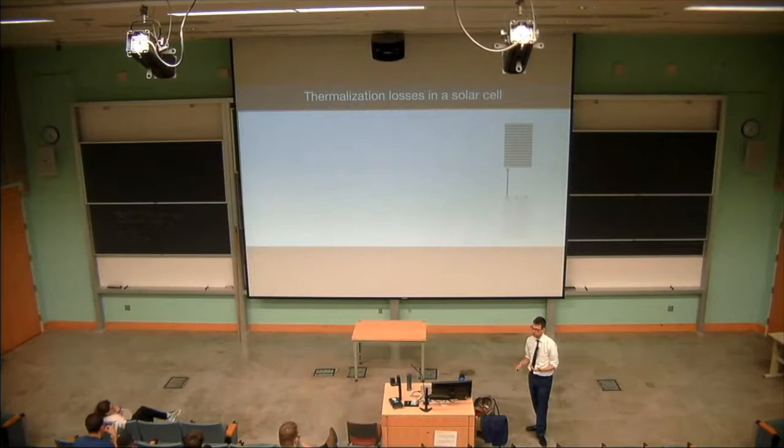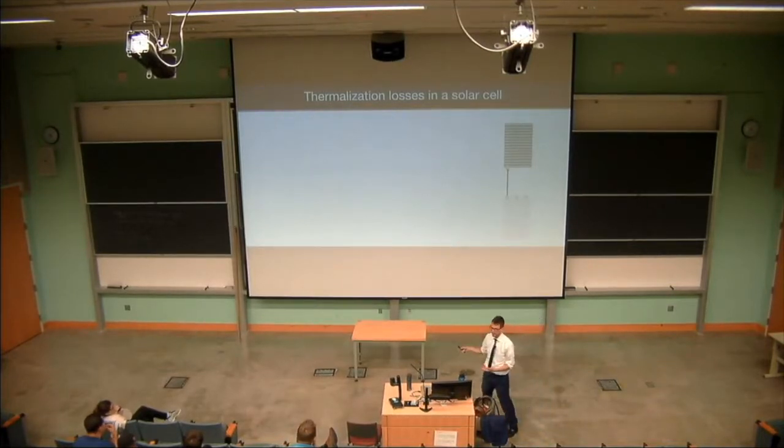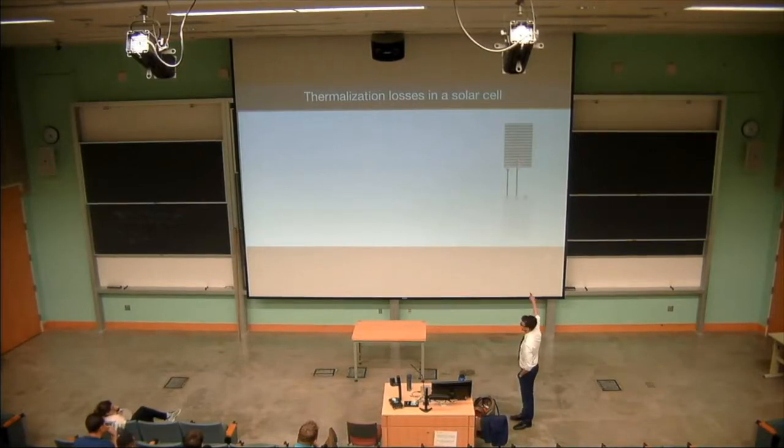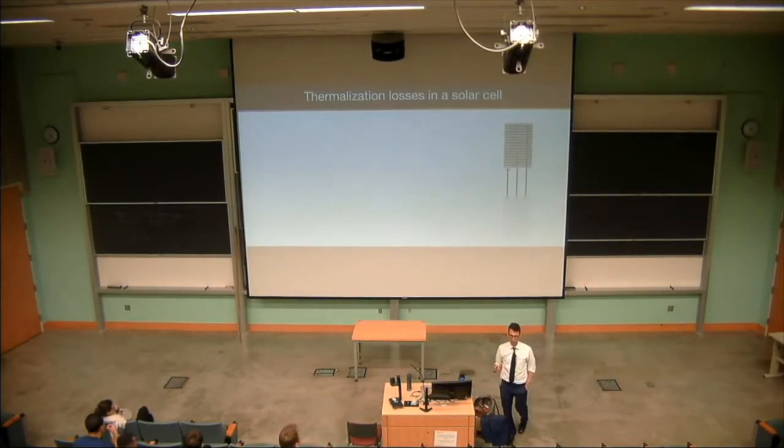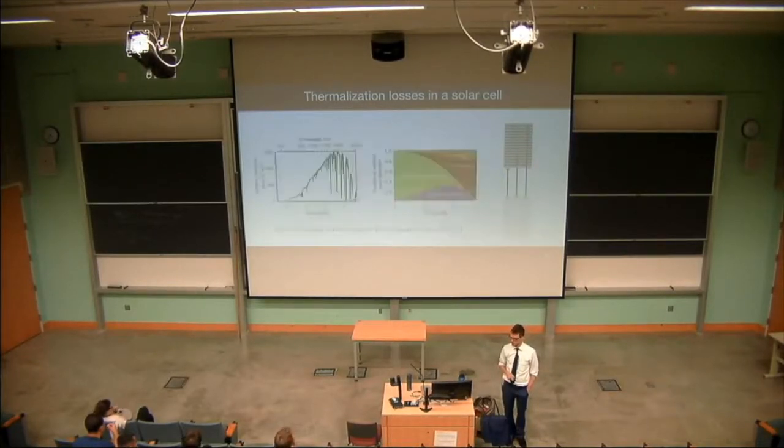The power you generate is always related to the band gap of the material, or really the quasi-Fermi splitting of that material. If you were to shine yellow light on your sample, this will excite, but this excited charge carrier will rapidly thermalize in your sample, meaning that you've now lost a bit of energy to heat in the lattice. And this only gets worse as you excite with higher and higher energy light in the sample. In total, thermalization accounts for about 30% of the lost potential power conversion efficiency in a silicon solar cell.